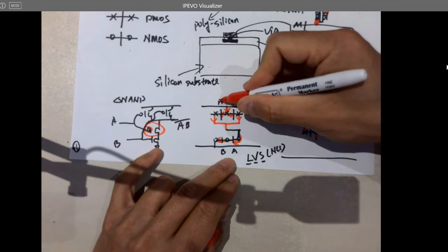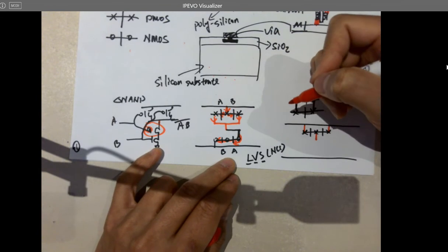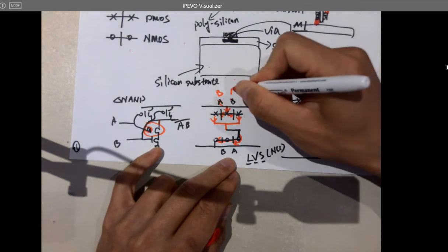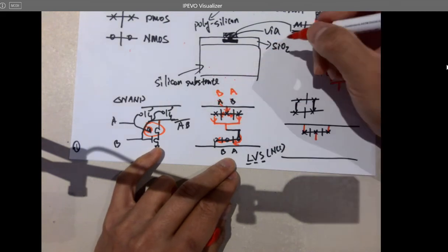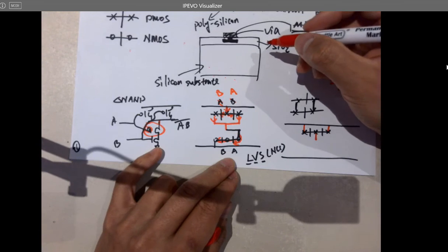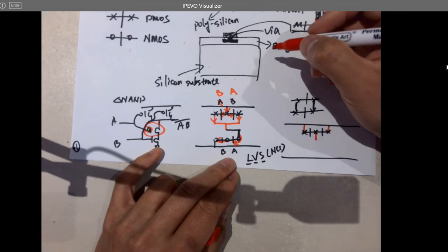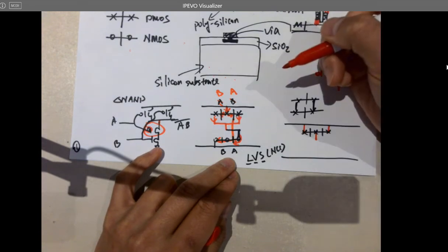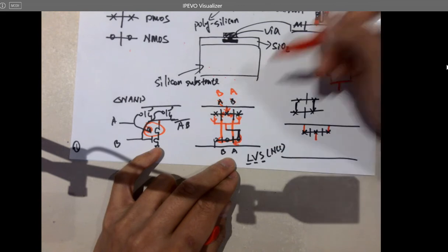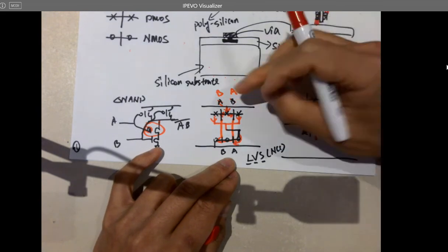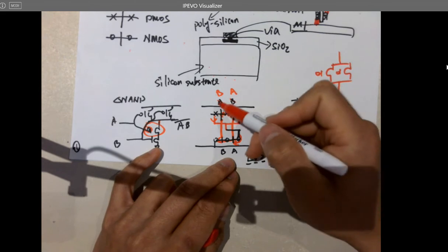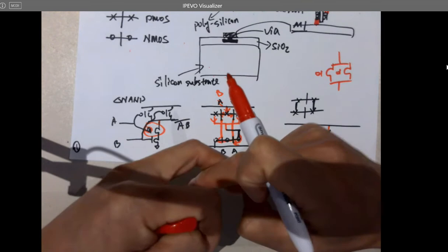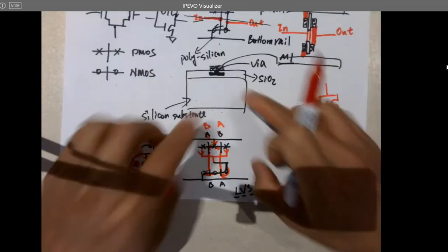And do you still want an A here, B here? It's not ideal, right? You probably want to swap them, even though it doesn't matter, but you still want to swap them. The reason is you want to short the gates together. If this is A, this is A, the two gates should be shorted together. And the two gates should be shorted together. And you can imagine if you have A here, then you have two poly layers, they're the same layer, you cannot cross them because it's going to short these two gates, because they are running on the same layer.